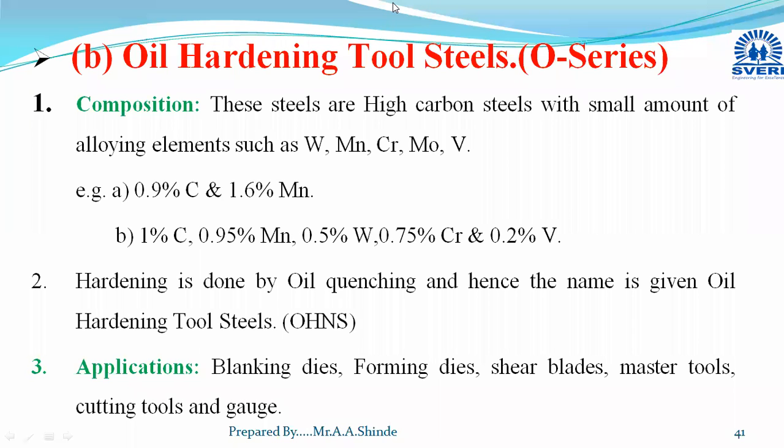After heating it in the furnace, we take it out and cool it with the help of air, oil, or water medium. This direct cooling method is termed quenching, used to get the desired hardening effect.